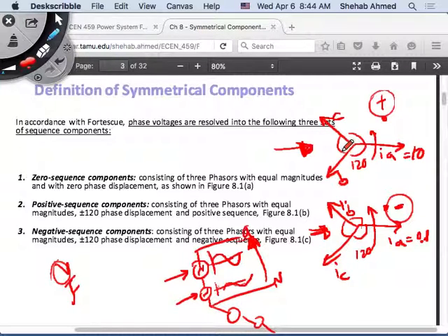Right there, you're losing torque density, and you would, of course, be losing efficiency because you calculate the amount of current coming in as well, right? So these machines will heat up. Anytime your machines are operating with an unbalanced power supply, they will be heating up. Harmonics cause unbalance. Failures in your system will cause unbalance.